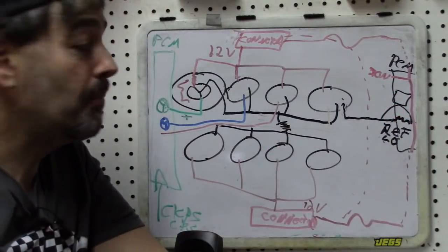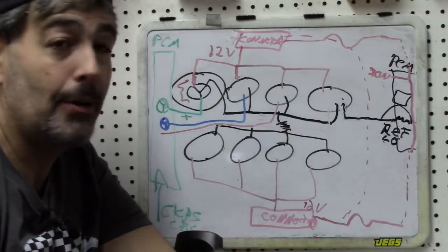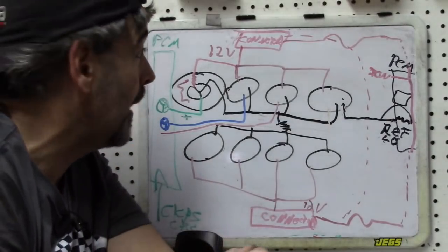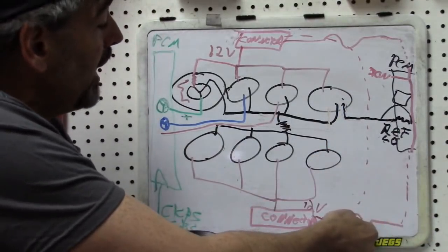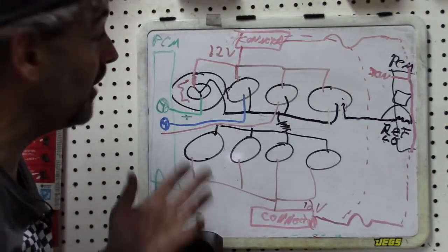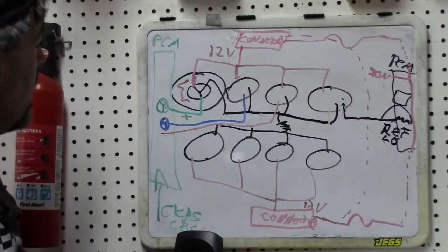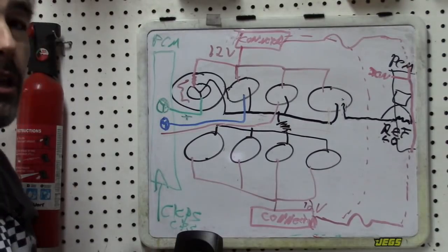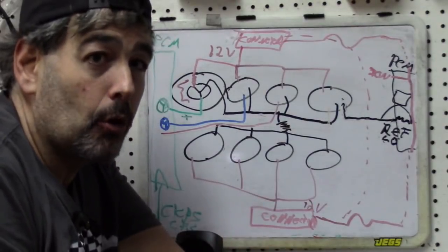it's still the same system that a lot of you more old-timers are familiar with, where it's directly with the key-on ignition switch. You still have to have the ignition on. It's just through the PCM, and it splits each bank with its own fuse. That's what I expect we're going to see. I may be wrong about that. That is our diagram. That is kind of messy looking. Let's see the actual diagram and see how correct we are.